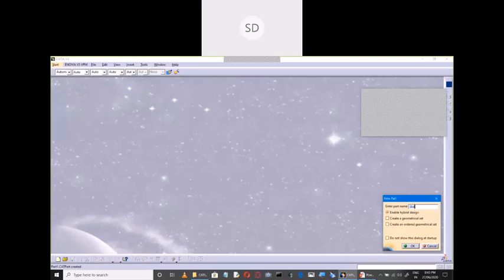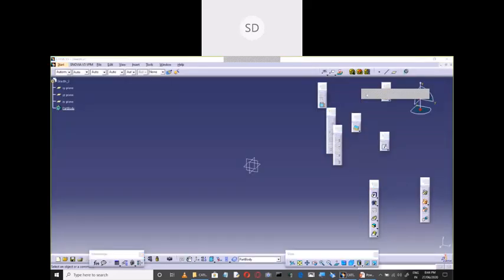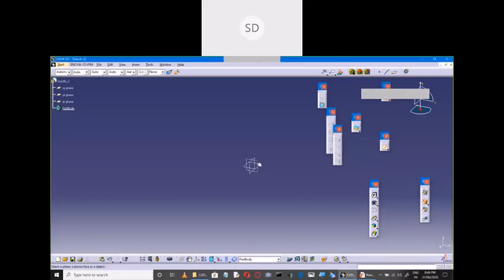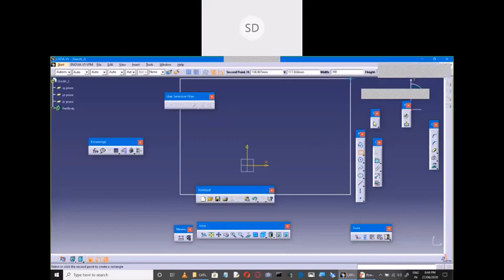So I can just go for sketch 2. Click on sketcher. Now select front view here. In this case, you can draw using the profile line continuously, or you can draw a rectangle directly. So we'll go for the rectangle directly here. I'll pick here. Now you need to provide width and depth. Width is 100.